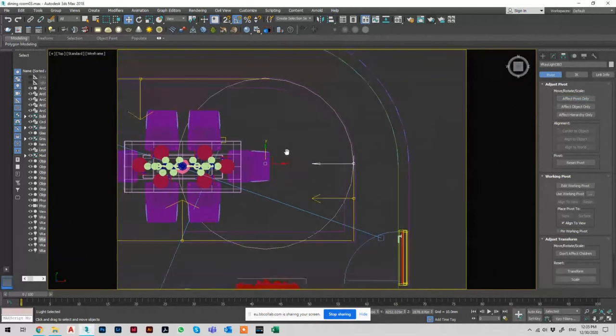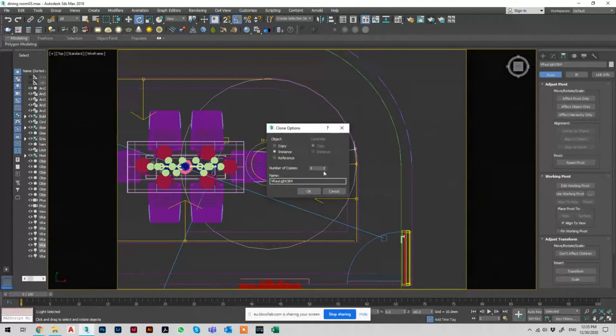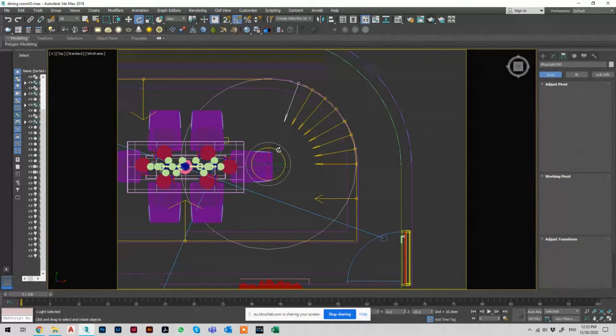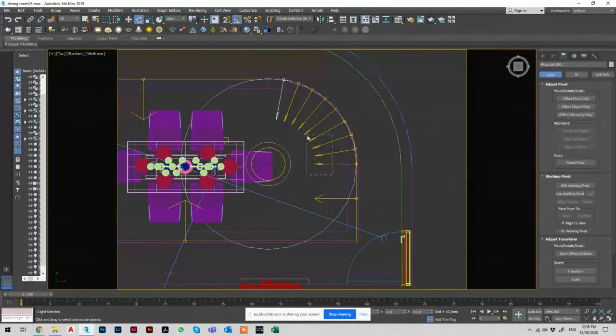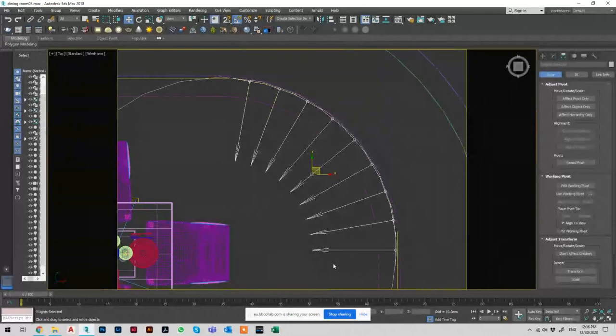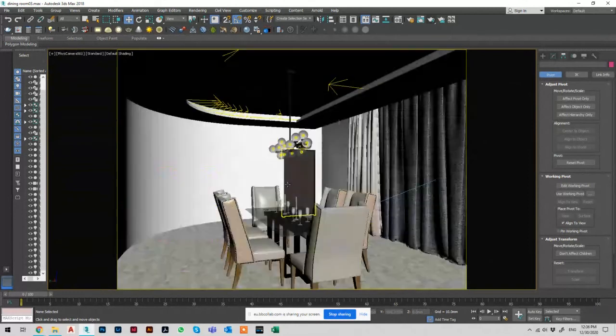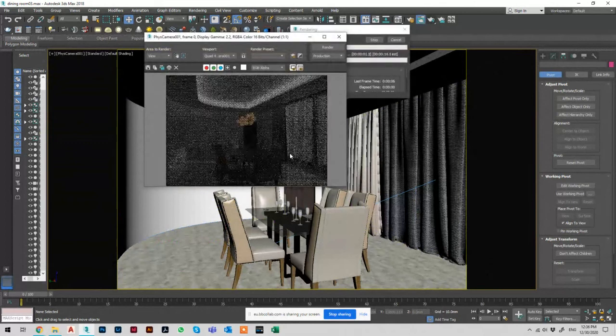Okay, this will help me in rotating the object. So shift, rotate. For example, 10 degrees is fine for the scale that I'm using, and then create these copies. If you need more, you can just rotate 10 degrees since you have object snap on. Okay, so just make sure that you select all of these, and then make sure that they're all inside. If you have any issues or your circle was not correct, you can move it this way. So this is the easy way to create these, and instead of rotating, copying, rotating, and so on, this would be easier for you. Then just make sure that the effect is fine, you don't have any issues. That's it, you can continue working regularly.